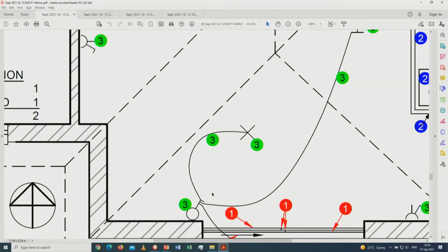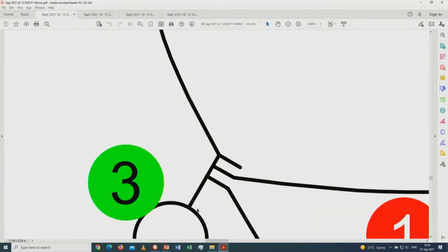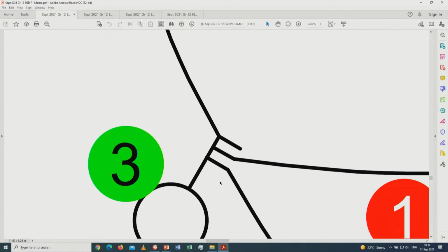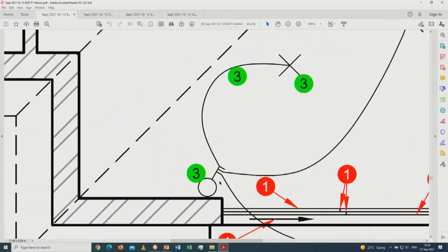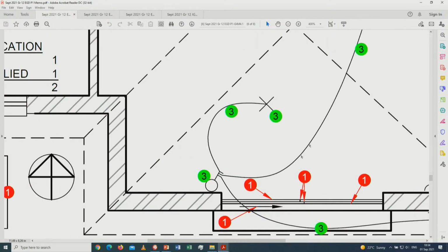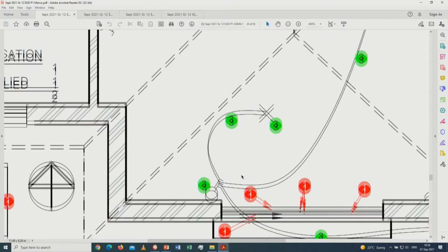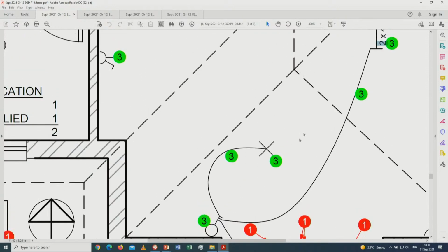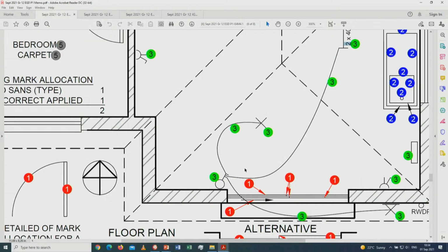Then this part over here, I just want to point out to you, in this case, there are 3 different lights, 3 different switches. So in that case, one goes up there, one goes to the other part, and one goes outside. If the learner has a line drawn from this line towards there, it's going to be wrong, because it points out it has to have 3 switches over there. Otherwise it's going to use one of them for both these 2 lights, which is wrong, and the other one will go outside. So that must be clearly stipulated over here.